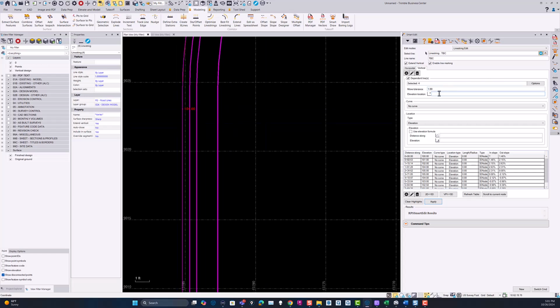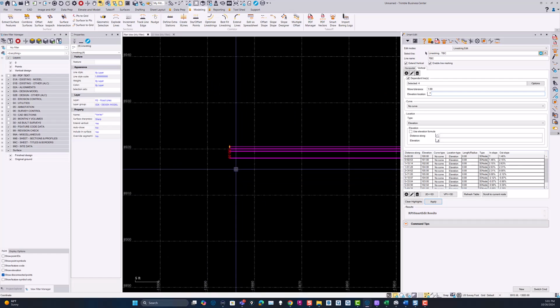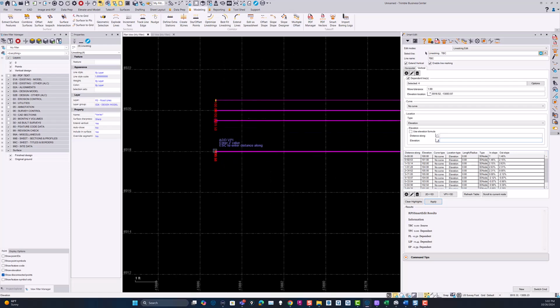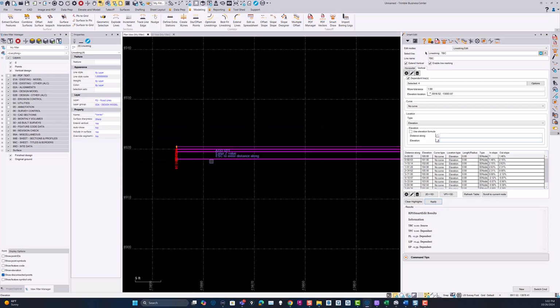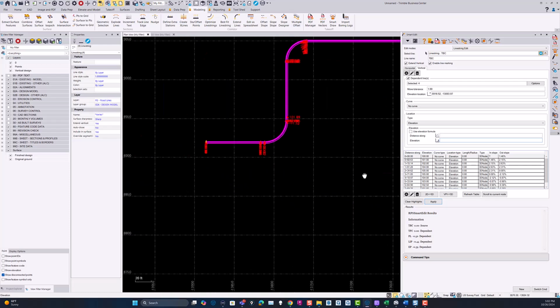And then you can say the elevation location, so you can pick a location on the line where you think that the offsets and elevations are representative of what these offsets should be. So I'm going to pick a point here, and at that point now it's elevated each of the ends of the lines to lock those in, so both ends now got elevated if they weren't already.